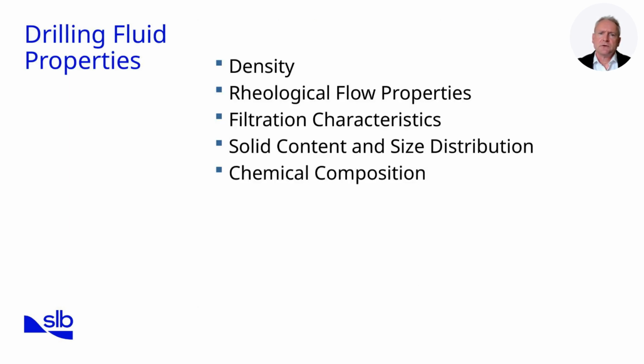Looking at the key drilling fluid properties affecting hole cleaning, the first property is density. This provides hydrostatic pressure to control formation fluids, but must be balanced to avoid excessive ECD and cuttings settlement. A density that is too high can worsen sag and increase torque. Second is rheological flow properties. These govern the fluid's carrying capacity. High viscosity enhances suspension of cuttings, but can increase pressure losses. Optimal rheology is crucial for transporting cuttings without requiring excessive pump energy.